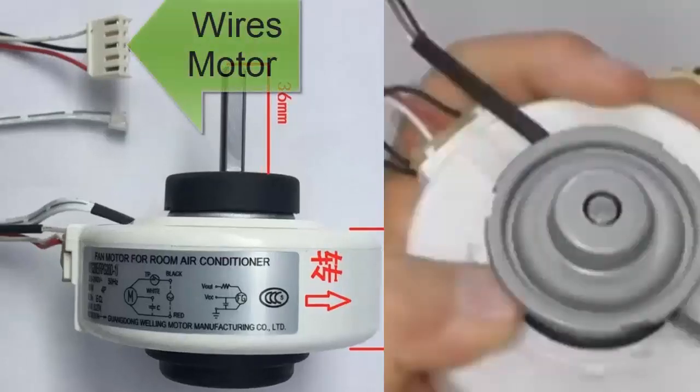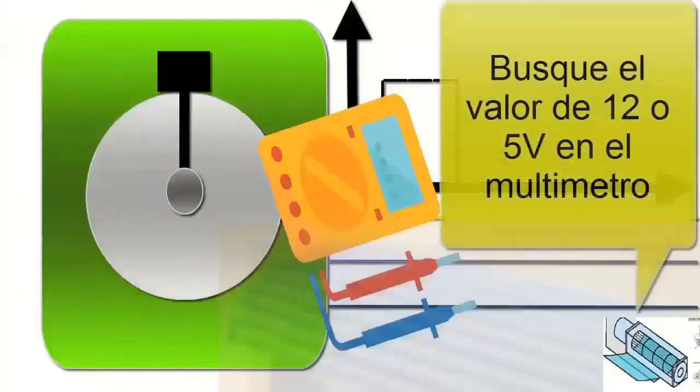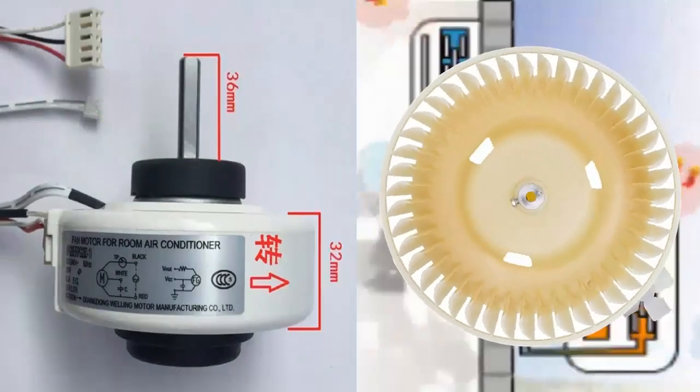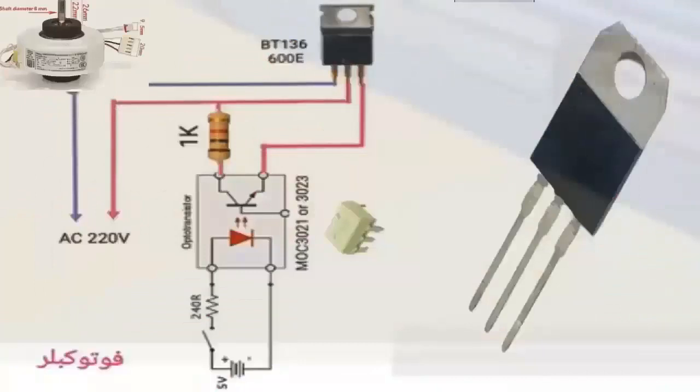For switching on and speed control, they use 3 wires of the same thickness. One connects to the common pin of the internal coils, another to one of the coils, and the third to the capacitor. The speed variation is done by varying the supply voltage, manipulating the voltage curve. They require a speed sensor, called a Hall effect sensor, which connects to the electronic board through 3 very thin wires, independent of the motor's power wires. Their most common failures occur in the capacitor, triac, bearings, and Hall effect sensor.